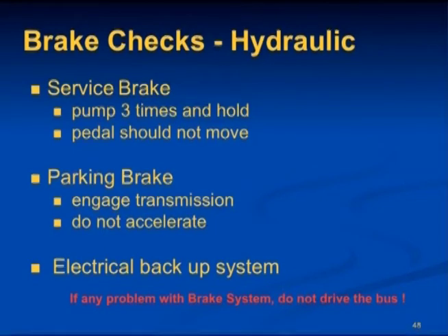Depress the brake pedal with the engine off. Listen to ensure the proper operation of the electrical backup system. Again, if there are any problems with the brakes, do not drive the bus.